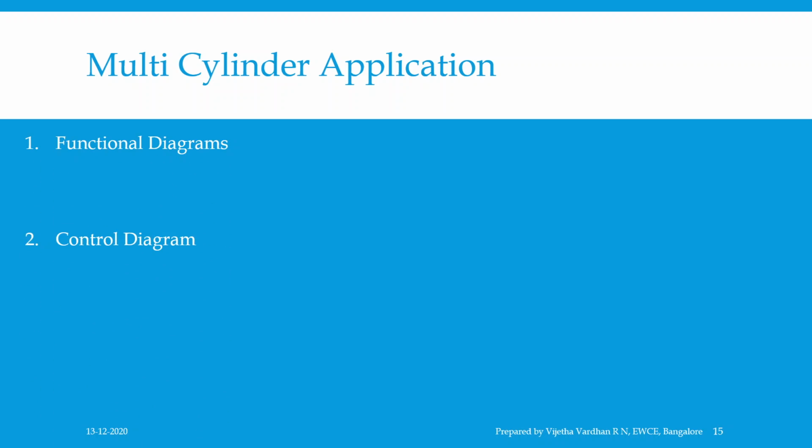Now first understand what is called a functional diagram. Functional diagrams are a graphical representation of functional sequences of different controls such as electrical, mechanical, electronics, pneumatics and hydraulics, as well as a combination of these controls, such as electromagnetic, electropneumatic, electromechanical or electrohydraulic, etc. The main objective of a functional diagram is to project a clear and distinct sequence of operation of all pneumatic elements used in a pneumatic circuit.